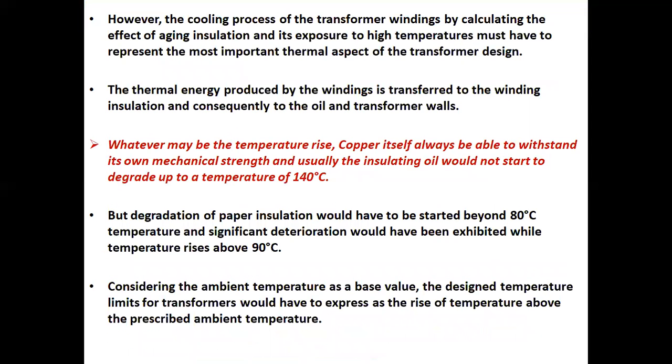However, the cooling process of the transformer windings, by calculating the effect of aging of insulation and its exposure to high temperatures, represents the most important thermal aspect of the transformer design. The thermal energy produced by the windings is transferred to the winding insulation and consequently to the oil and transformer walls.